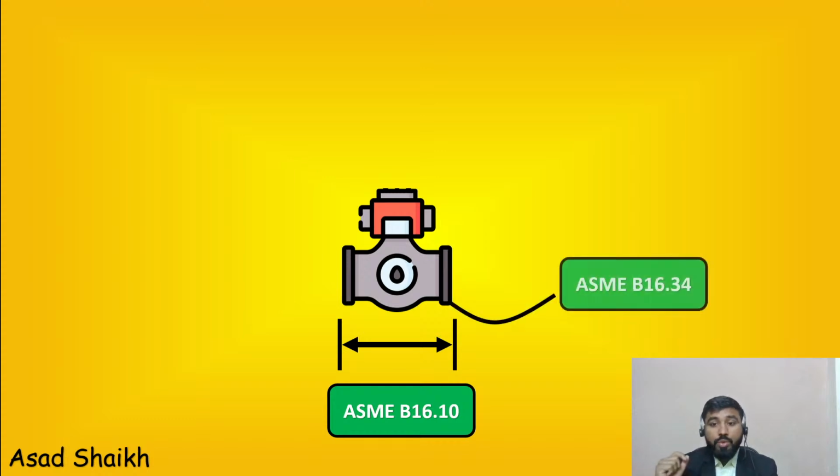Next, after that is going to be your flange standards. This is ASME B16.34. If you look in the standard ASME B16.34, it has various classes: standard class, special class. Usually 99.9% of your projects will be going with the standard class. Check the PT rating based on your standard classes. As somebody said, if your pipe material was carbon steel and your valve is 316L, it might not have the same rating, so your rating will increase, and similarly the pipe rating has to be increased to match the valve with the pipe.